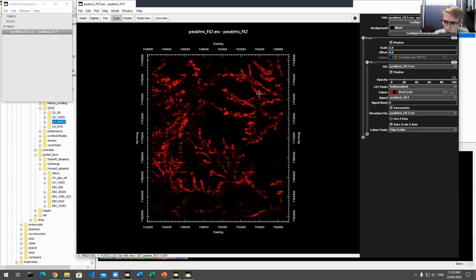And we do begin to see these horizontal lines appear throughout the data. These are in fact poorly leveled tie lines. So this was a really quick way to identify whether tie lines have been correctly leveled or if they've been ignored. This is where we would want to go back to our tie line leveling or to our gridding process where we specifically say to ignore the tie lines.